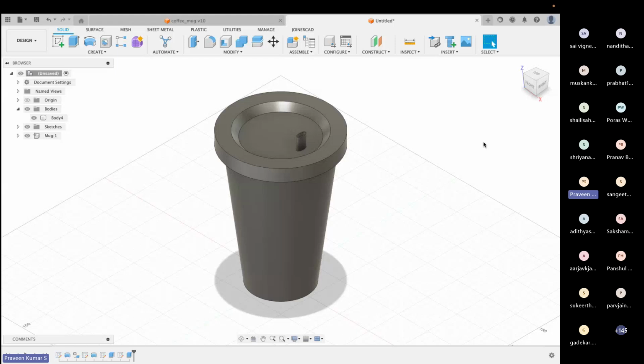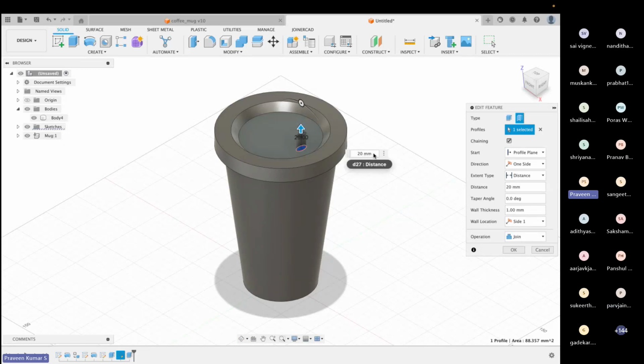So we make another ellipse. We made the first ellipse to extrude it and cut it downwards, right? Yes. So make another ellipse on top of that. That's because Fusion doesn't let us do upwards and downwards at the same time. So you make another ellipse on top of that and then click extrude. Okay. So click extrude and you give a dimension of 20 millimeters upwards. Yeah, upwards. Okay. And then give thin extrude, this option here, which after clicking extrude, you'll get two types. So don't give extrude, give thin extrude and just click OK. Make sure the operation is join and click OK. Okay.